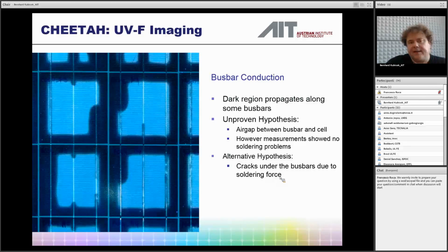It could be that the busbar is soldered in most parts, but has a small air gap at the sides, or maybe a little bit underneath, where you can have additional diffusion or faster diffusion than through the EVA. And sadly, we failed to prove any of those. Some of what you could use is ultrasound microscope, and we couldn't see any cracks there. In some cases, what we did with electroluminescence, we very often couldn't see any cracks either. However, if it would be directly under the busbar, we wouldn't see that.